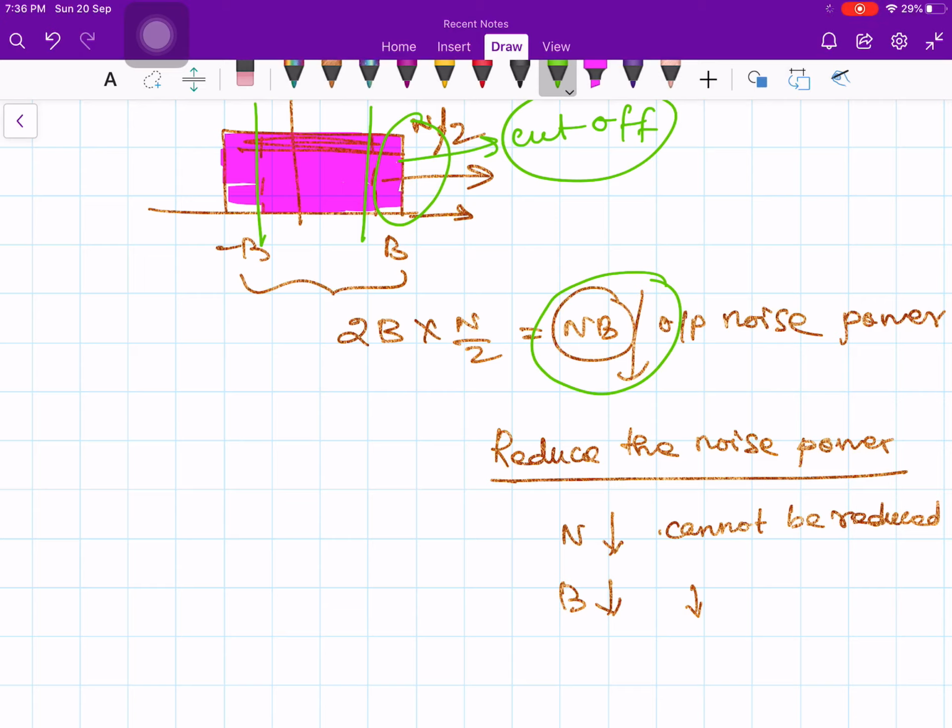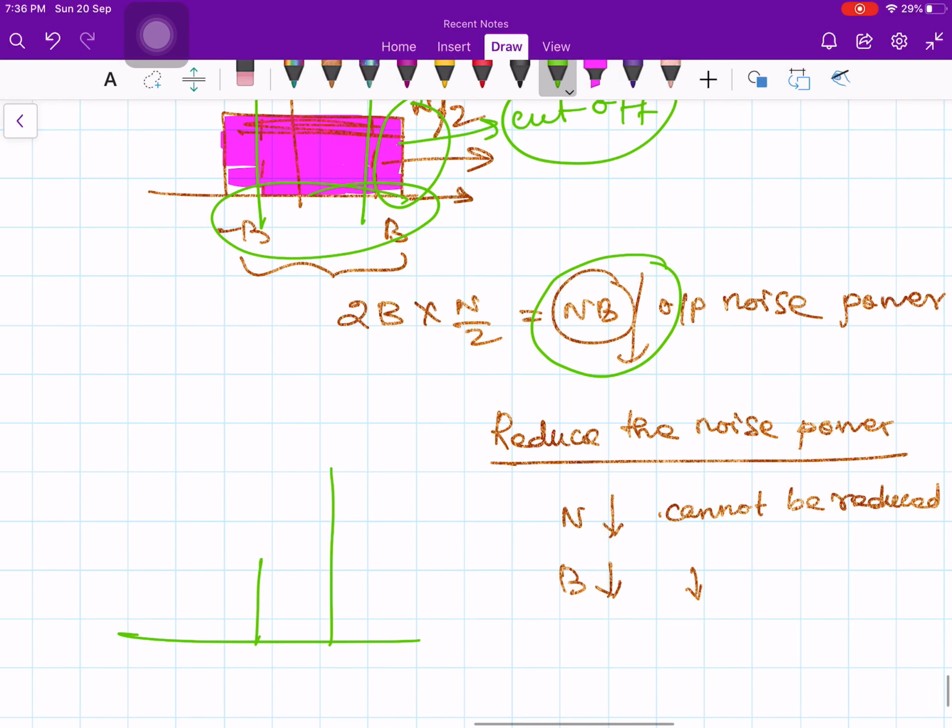So this is the noise that will come through if you want your signal to come through. Okay, if the signal has this much bandwidth, minus B to plus B, therefore you have to have a filter with this much bandwidth. You cannot have a filter with smaller than B hertz, I mean minus B to plus B. In case you have a filter like this, minus B and plus B, then what will happen? Your signal will get distorted, because higher frequency components are eliminated. Then a human voice will look like somebody else's voice. A donkey voice will be heard as a buffalo voice or something else, I don't know.